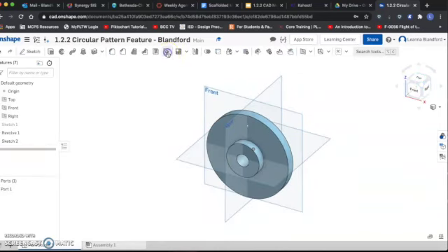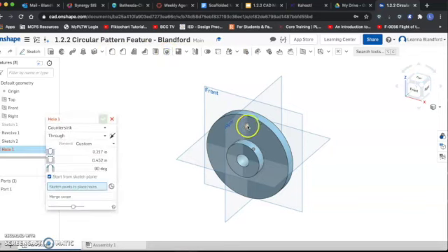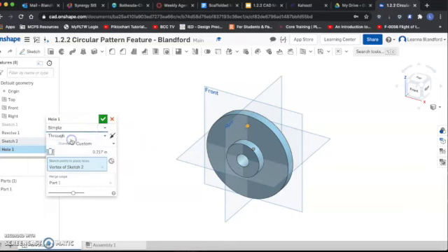So I'm going to close that sketch, and I'm going to rotate back to my isometric view. I'm going to select my hole tool. I'm going to pick this right here, and then I'm going to change this to a simple hole and through. And what I am then going to do is set that diameter to its correct diameter, which is, I believe, 0.5.